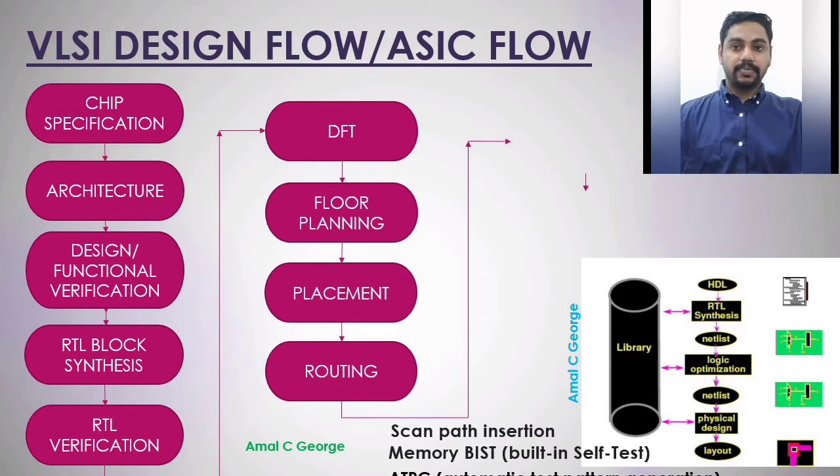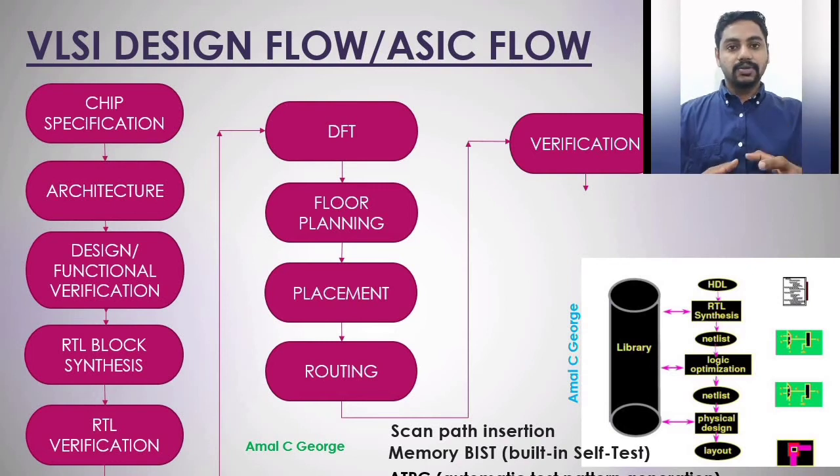The 10th step in our design is final verification or physical verification and timing. So after routing, the ASIC design layout undergoes three steps of physical verification known as sign-off checks. This stage helps to check whether the layout works the way it was designed to. They will check layout versus schematic LVS, then design rule checks DRC, then logical equivalence check.